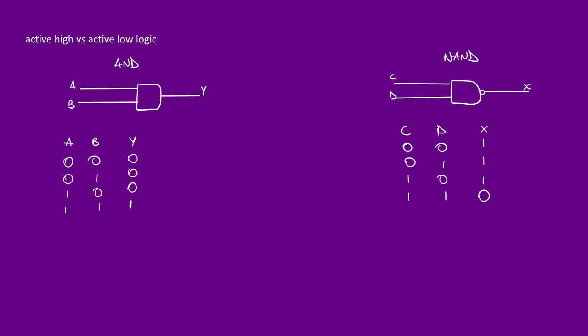So what does this mean for us as we're handling digital electronics? It means that my AND gate is able to tell me that, out of the 4 combinations of inputs, when I have both of my inputs high, then my output is going to be high too. Which is why you will sometimes see that the AND and NAND gates are the simplest decoders, the 2-input simple decoders. Look at it: out of the 4 possible outputs, 1, 2, and 3 are low, and this is high only when these two are activated.